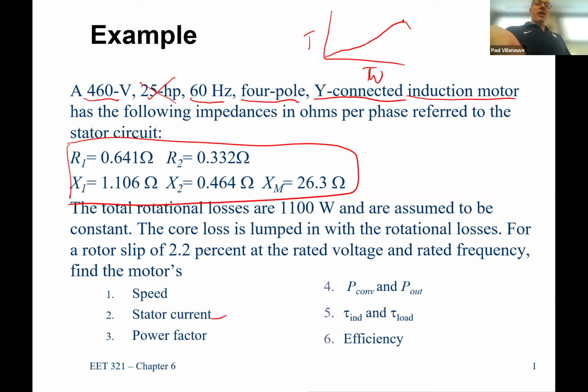So the reason why you can't use torque is because you need to know what speed of operation it's going to be. So that again is going to have to come from the mechanical engineers. The mechanical engineers are going to say that this torque versus speed curve is at about here, and I need you to give me 22.3 horsepower at 1650 RPM. And then you would specify the motor application.